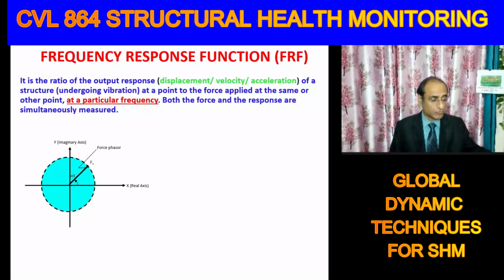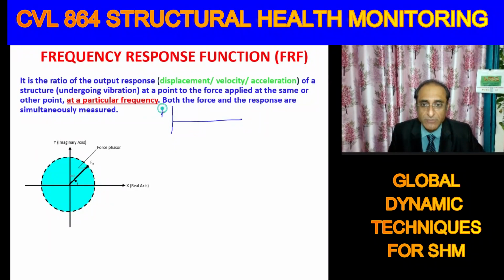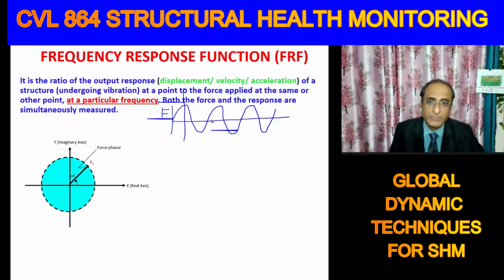Now let me ask you a question. Let's say you are applying a force, and this is how the force varies with time. Let's say we use a sinusoidal function, or if we shift our reference here, a cosine function. Either a sine or a cosine function can define a force. Now, if we measure the displacement, you will find that force and displacement have a phase difference. First of all, what do we mean by phase difference? I am using red color to define the response. You will find that the displacement will inevitably lag behind the force.